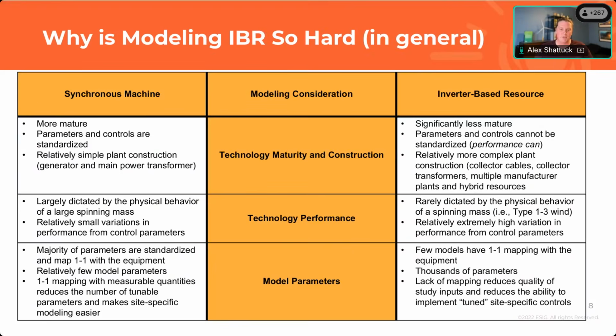the inputs and reduces the ability to actually tune something for an IBR and actually put it into the system. Right? If I fix a controller interaction, I might not be able to put that same tuning into the system and fix the real controller interaction. So that's in general why it's difficult to model inverter-based resources, everything on the right.